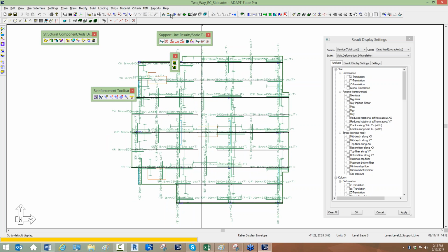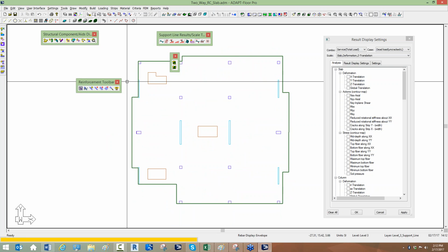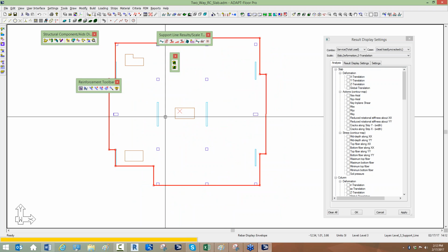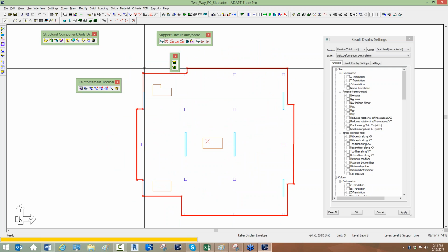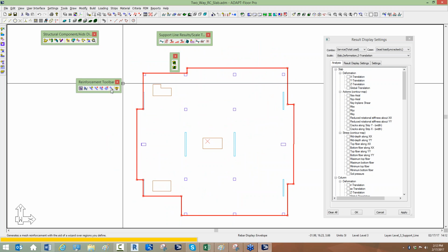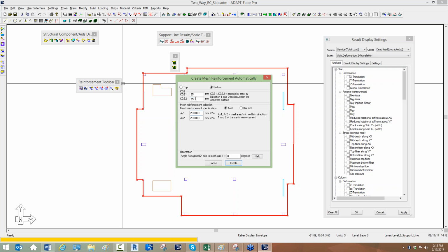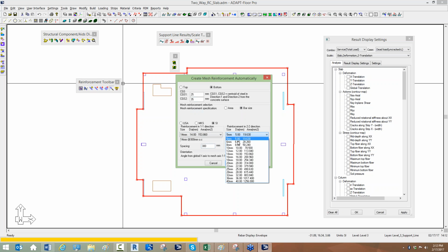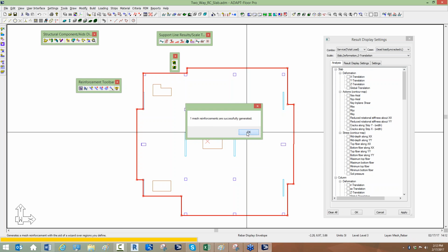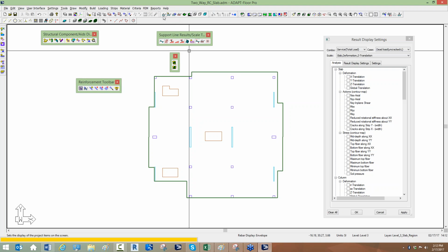As the user, you have the ability to add rebar to a slab. So if you know you're going to add number 5s at 18 inches on center, top and bottom, you can go in here and map mesh reinforcing to a slab. I can use the wizard and I can say, well, I know I'm going to add that rebar to this slab, and we might use number 5s, or let's say this is, I keep forgetting this is metric, 14 millimeters at 300, both directions. We'll say okay, and that's bottom reinforcement I think that I just added.